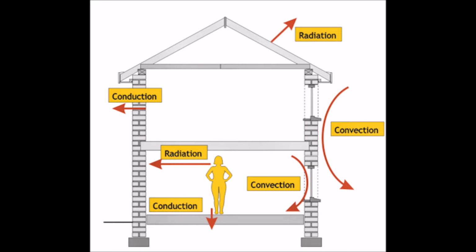An insulating effect can also be achieved by the thermal mass of building components. Thermal mass describes the ability of a material to absorb, store, and release heat energy. Thermal mass can be used to even out variations in internal and external conditions, absorbing heat as temperatures rise and releasing it as they fall. In building design, this can be useful for evening out and delaying extremes in thermal conditions, stabilizing the internal environment and so reducing the demand for building services systems.